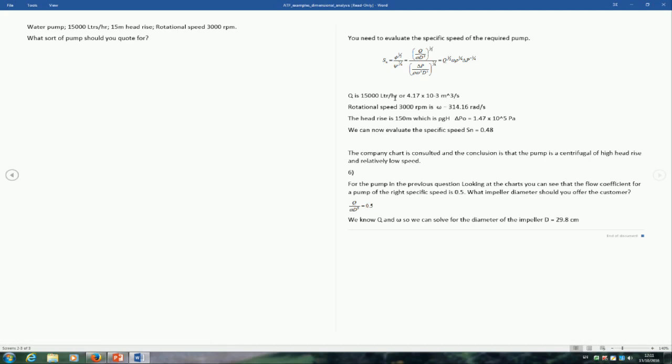It's just horrible units, cubic feet and RPMs and all sorts of stuff. But the idea is the same, but they never get non-dimensional. They're not bothered about it. And they still call it specific speed. This is real specific speed, non-dimensional specific speed.